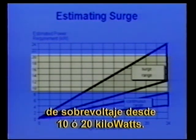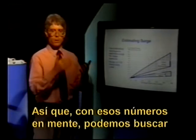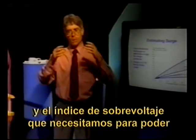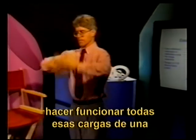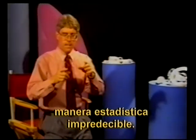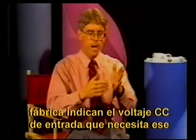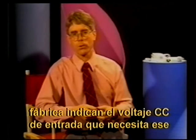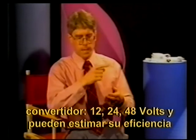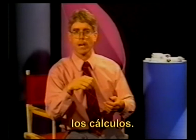10 and 20 kilowatts. So with those numbers in mind, we can search through literature and choose an inverter that gives us the continuous rating and the surge rating that we need in order to operate all of those loads in an unpredictable sort of statistical way. Again, once you've chosen the inverter, now from the manufacturer specifications, you have the input DC voltage that inverter needed, 12, 24 volts, 48 volts, and you can estimate its average efficiency. And that's what we're going to need to continue our calculation.